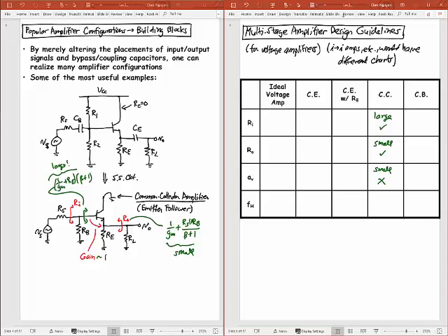Now, in terms of frequency response, what can we say about this? The main capacitor is the capacitor between the base and the emitter. Remember, I have a gain of 1 across that, so that capacitor gets knocked out. I don't have any gain really from here to up here, very small gain, so C mu is not multiplied by a Miller multiplication.